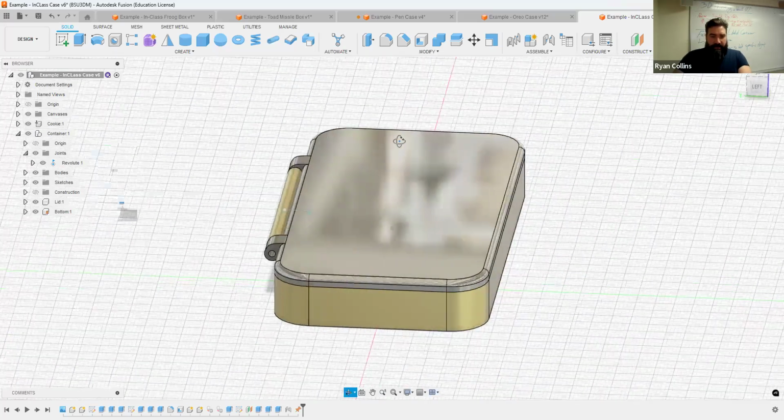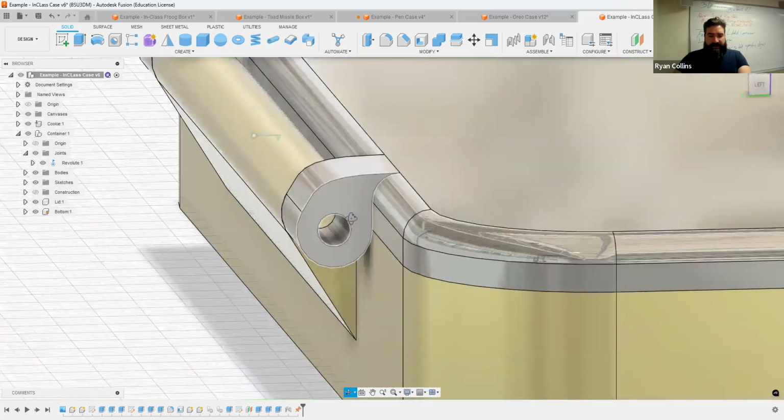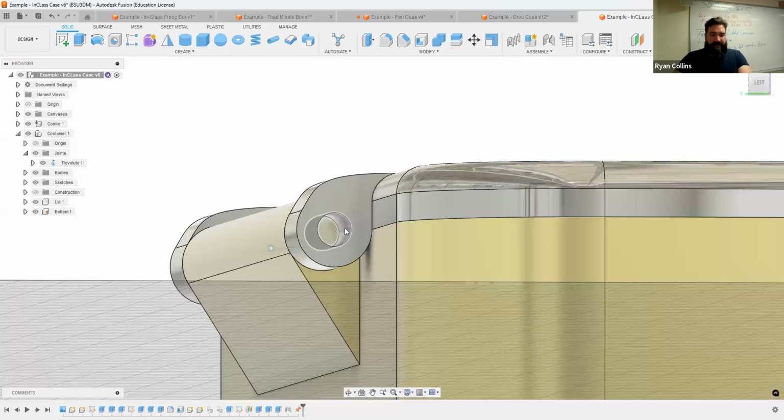But first, we need a hinge for this. We need a pin for this hinge. So I modeled this to the size to actually consider being able to print this or use just a length of filament fed down that hole, and then a soldering iron or something, and just sear the two ends, and instantly you've got a pin.